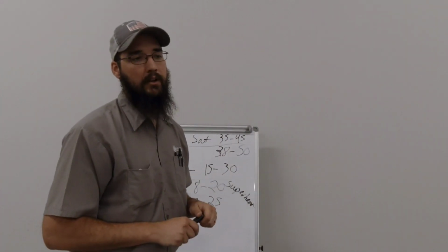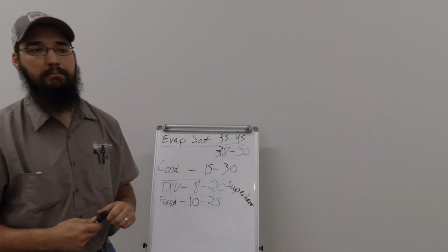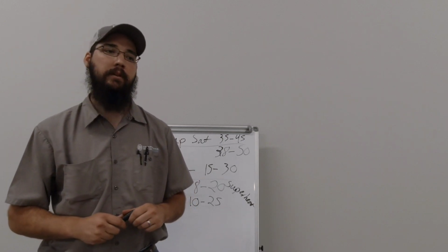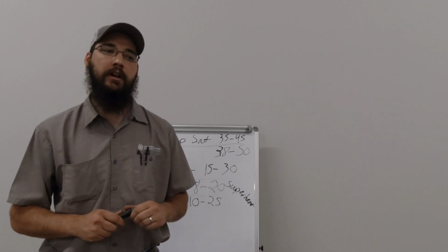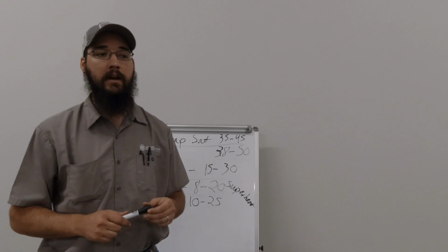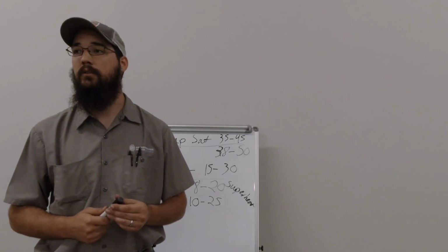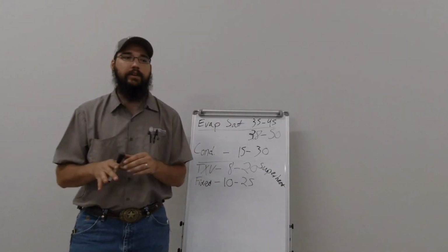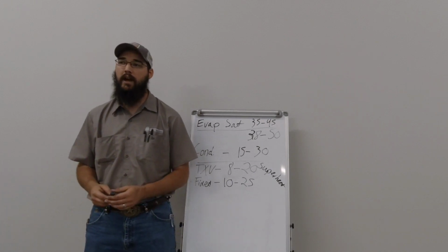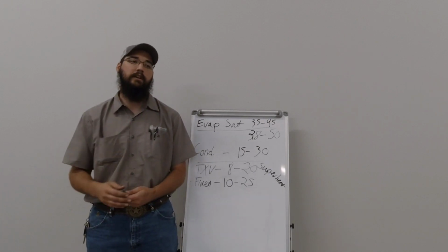Usually if I'm going to go in and do a TXV calibration, I'm preparing for a minimum 2-hour process. Minimum. I've spent an entire day trying to tune. Actually, that exact IntelliPack I was telling you about took us about 6 hours total. Just a side note, TXVs, you have to wait for them to settle. That's one thing great about things like the Testo apps, is you can chart your readings.